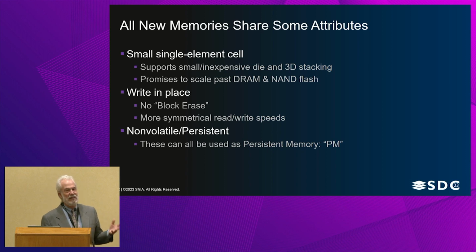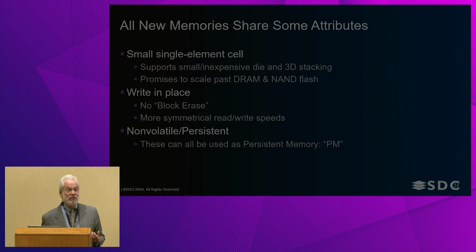And they also offer much more symmetrical read-write speeds. Usually the writes are less than 10 times as slow as the reads. And very often they'll be only 2 times or 3 times the time. So that means that they're very fast memories in comparison to NAND flash. They're much easier to use.